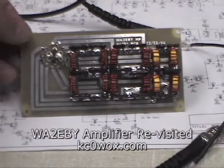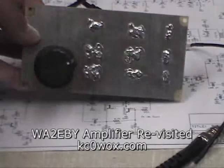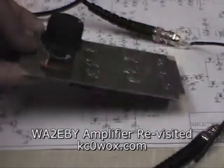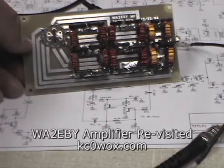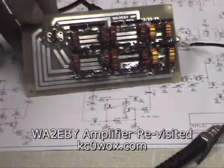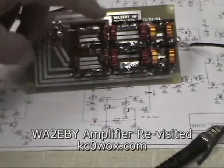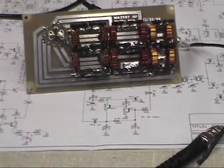Let's take a look at a WA2EBY amplifier low pass filter board. This has got a 160 through 10 meter low pass filters built into it. There's about six different band positions, 1, 2, 3, 4, 5, 6. Each one of these is a low-pass filter and selected by the switch. So let's hook that up and see what that looks like.